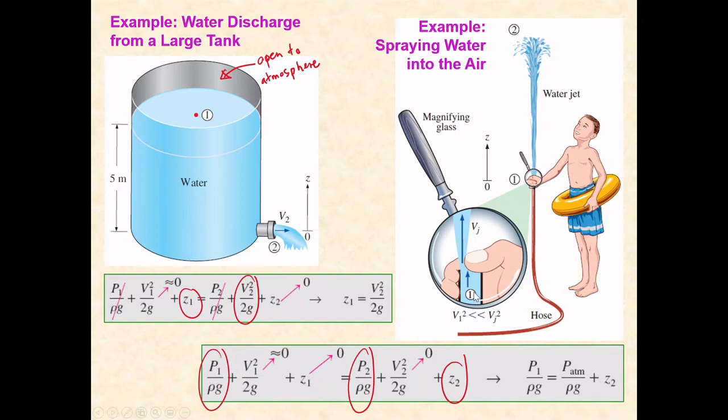So in this case, we can look into P1. Because the boy uses a finger to close a portion of the cross-section area, which tries to restrict the water from going up, the pressure is building up within the pipe. So we have some pressure P1, and at P2, we know that P2 will be at atmospheric pressure.